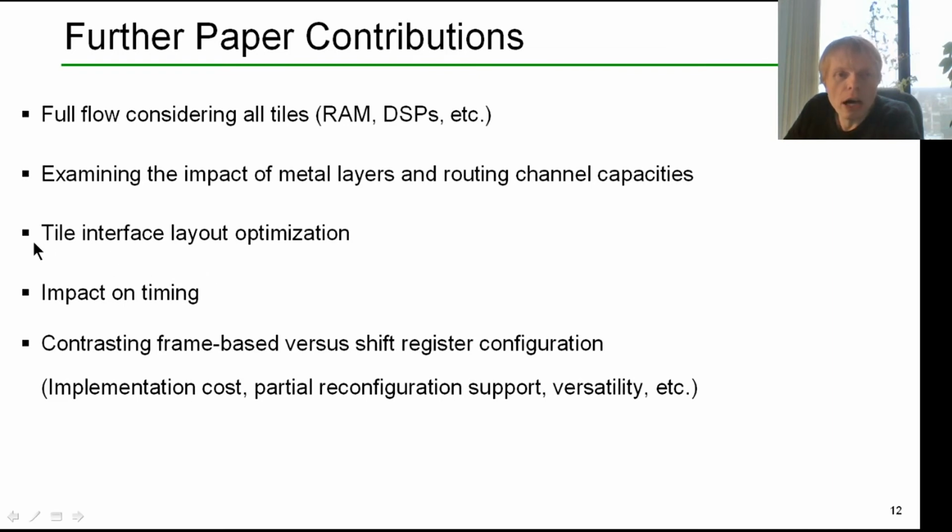I mentioned the tile interface optimization, but in the paper is also the algorithm and how we did this. We have some figures on timing in the paper. We don't have anything on power, as we don't have reliable enough estimates for that one, but we can probably assume that power will be better, because if you have shorter wires, you have less parasitics, and that will typically help you. And the paper provides a discussion about frame-based versus shift register configuration.